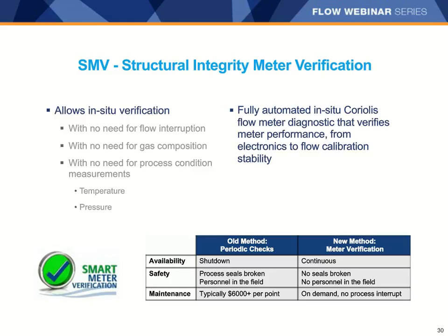It improves safety by preventing you from having to send someone into the field, and it avoids breaking seals in the gas line. Once SMV has been purchased and installed as part of the meter, there are no additional costs to run a test, so you can run as many tests as you want, as often as you want, without incurring any additional cost. I should pause here and remind everyone that Coriolis meters are extremely unlikely to be damaged in service,